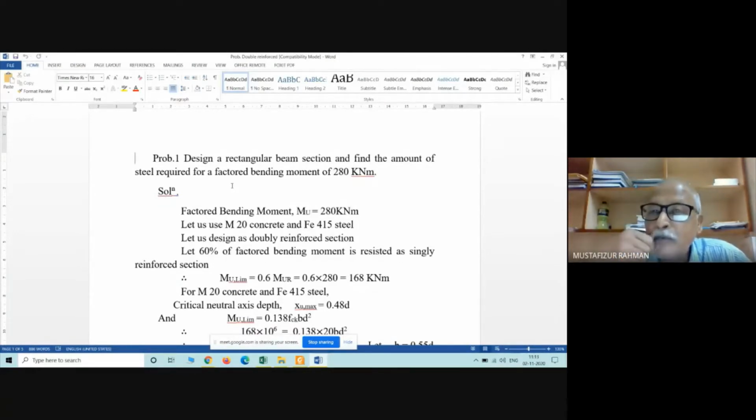As per IS 456, as well as IS 1893, which we will learn later, for structural concrete the minimum grade of concrete is M20, and for steel normally it is Fe415. Even we can go to Fe500, and now even Fe550, right? Normally, M20 and Fe415 steel is utilized.